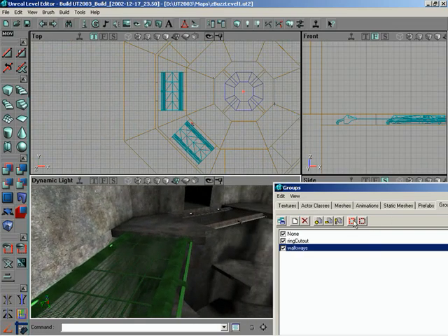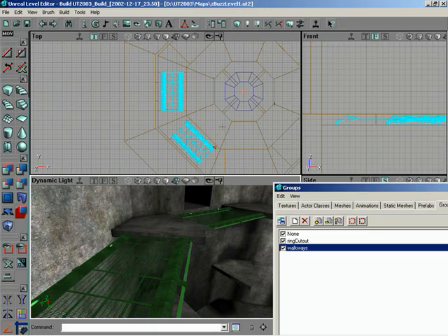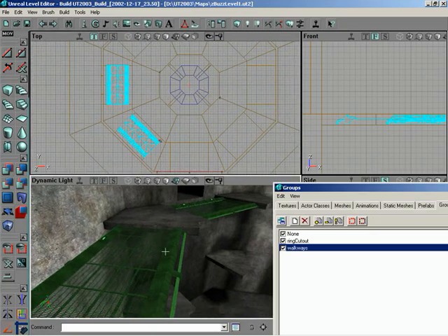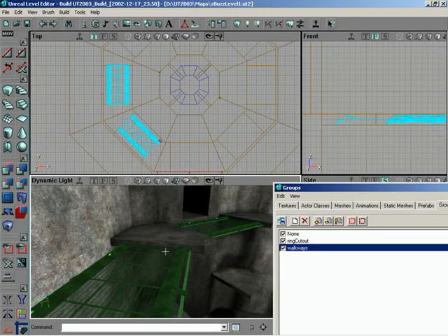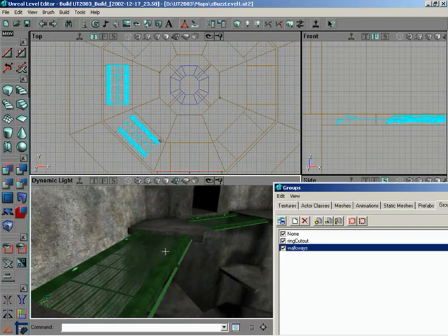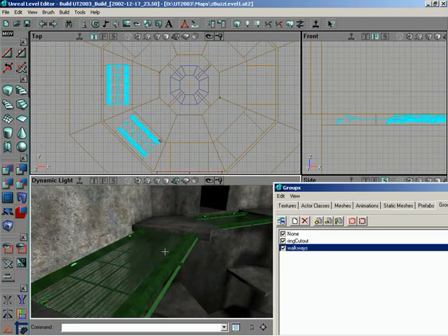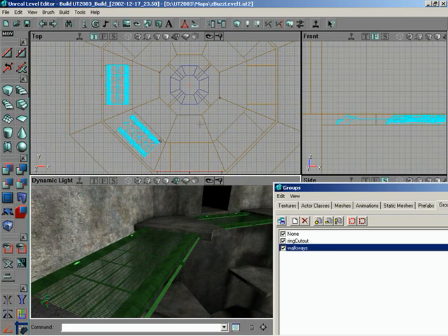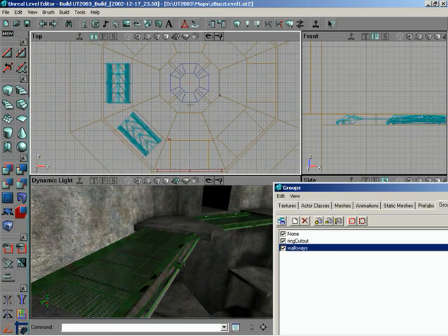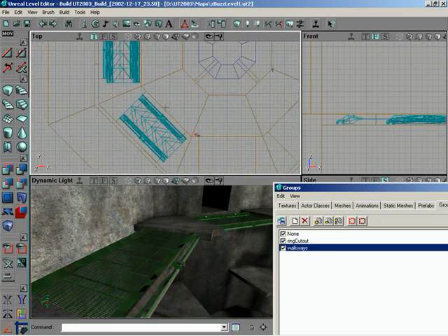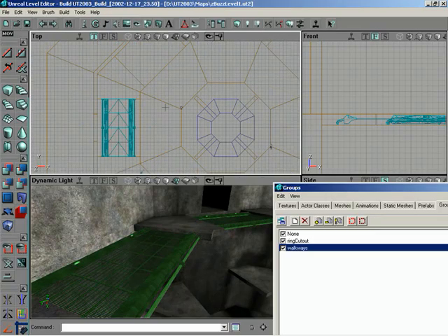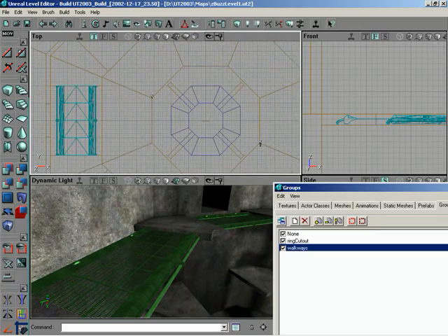I'll hit Select All, and we have a slight draw bug on showing the selection of static meshes, so I'll often use perspective to verify certain selections. Alright, so now with 2 spanning walkways selected, I'll Control W to duplicate again, zoom in a little so I can center these back up, then center their pivot to the center of the world.